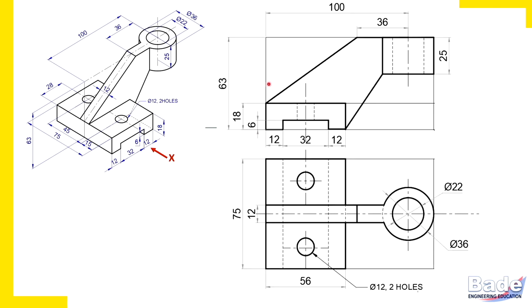And then insert dimensions. You are asked to insert 6 dimensions. I have inserted here all given dimensions. Remember, the nearest dimension line must be at least 6 millimeters away from the boundary. This is parallel dimensioning, 2 parallel dimension lines at least 6 millimeters away from each other. Then here, take care of all details of dimensioning. As far as possible, we don't insert dimensions in between the views, but here I have inserted, because it's always better to insert dimensions closer to a particular feature.